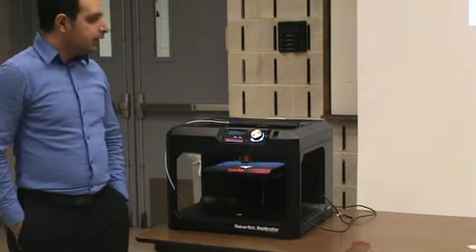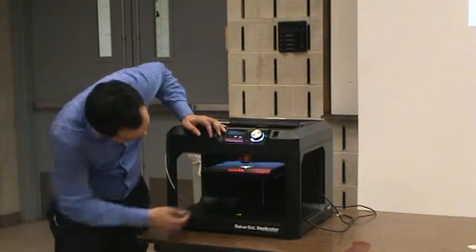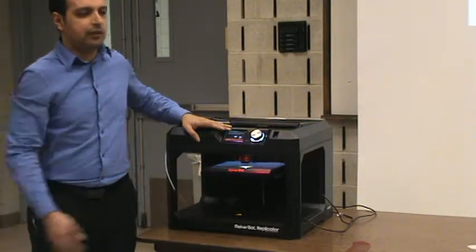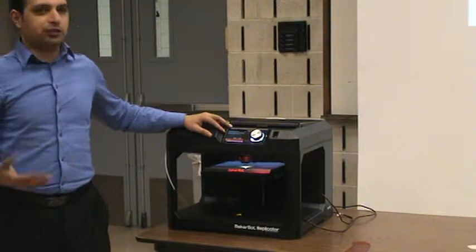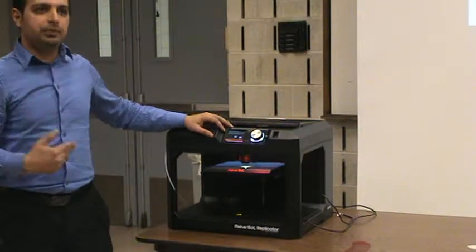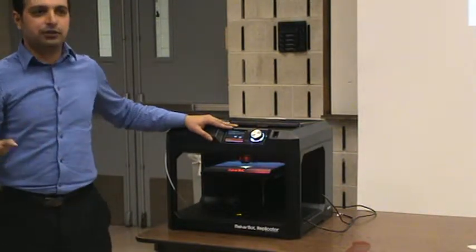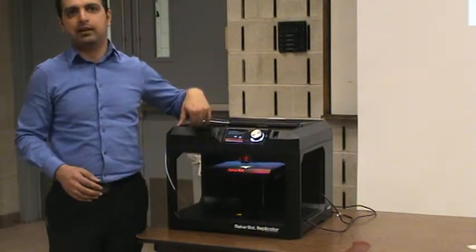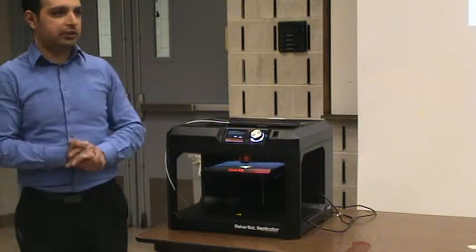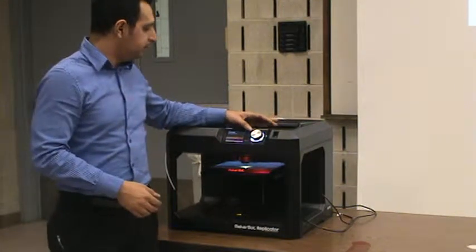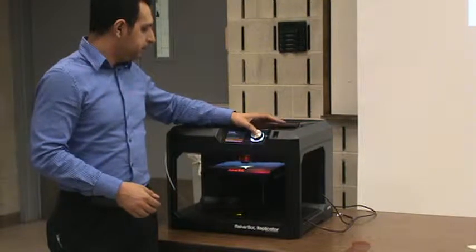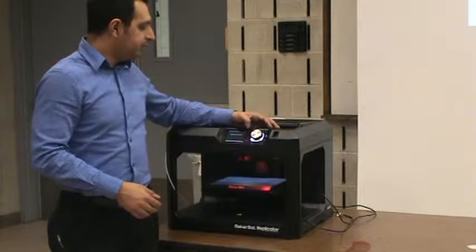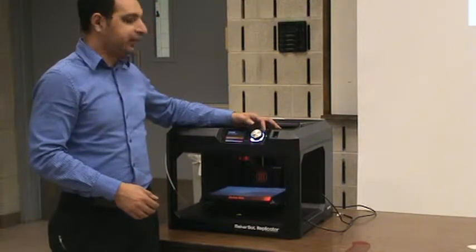This one is calibration, right? Yes. There are two nozzle knobs here that you can turn to calibrate it, so make sure you calibrate it yourself so you know how to use them. Every print should be preceded by a calibration. First you unload the filament, calibrate the plate, load it back again, and then you can go ahead and print. There is also an option to preheat the filament, so before you print, make sure that it's preheated.